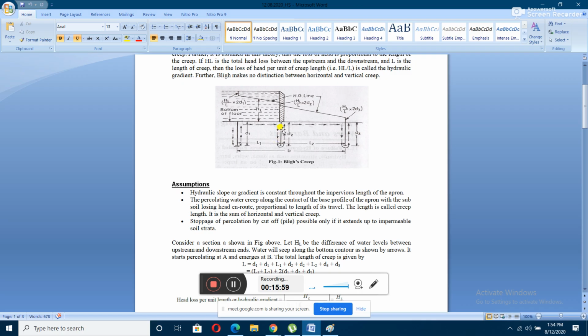If you can see the figures of the vertical drop weirs, your rock fill weirs, and another one was the concrete weir, as per the note I have given you, you can see that three piles were being used. One was at the upstream, one was at the downstream, and another one was at the intermediate position, right at the construction of your wall face. There was another pile being inserted.